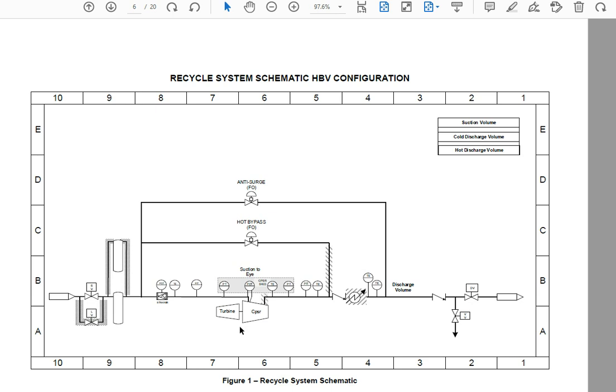Well, what I do is I look at fast stop data from machines I've worked on in the field. So I have high-speed trends, and I look at the decay of power turbine inlet air pressure. So in the case of these typical turbines I work on, I'm looking at compressor discharge pressure from the gas producer. I don't have the data of the air pressure at the inlet of the power turbine, but the combustor inlet pressure, the PCD, is pretty representative. So I look at the decay of PCD in time, and that's how I develop my models for rate of decay of power. Is that important? Absolutely.